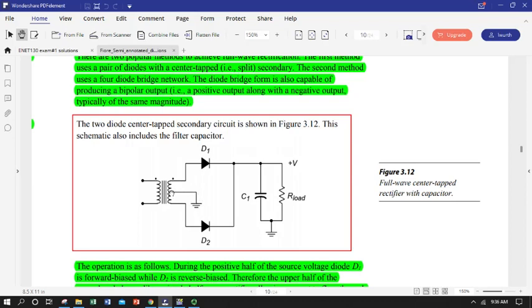So basically our secondary waveform, when it goes full positive at the high point of our forward cycle, we're going to have our positive voltage being seen up here at one end of our coil. We have 0 in the middle, and then we'll have negative at this end.